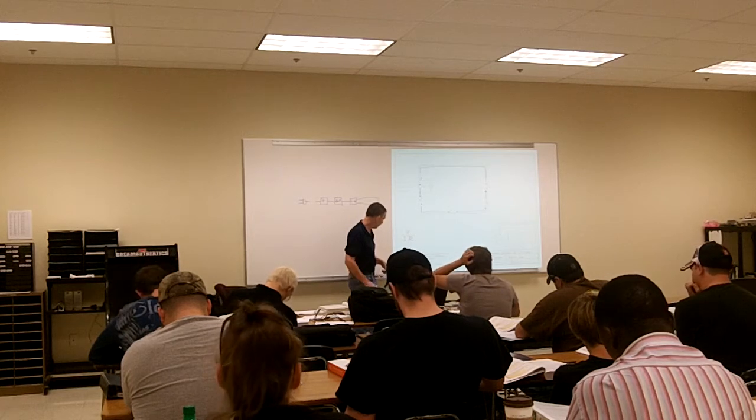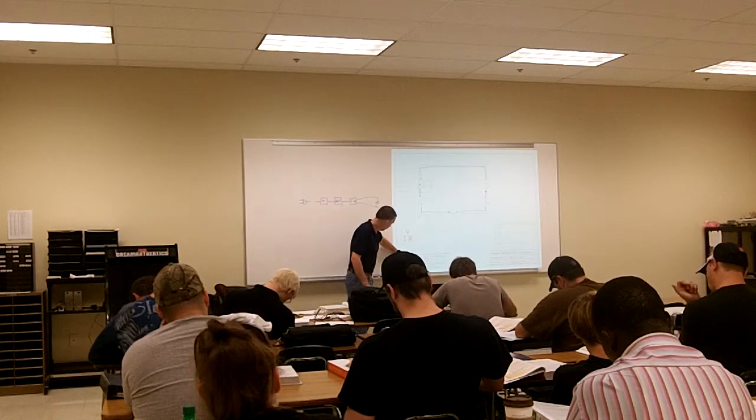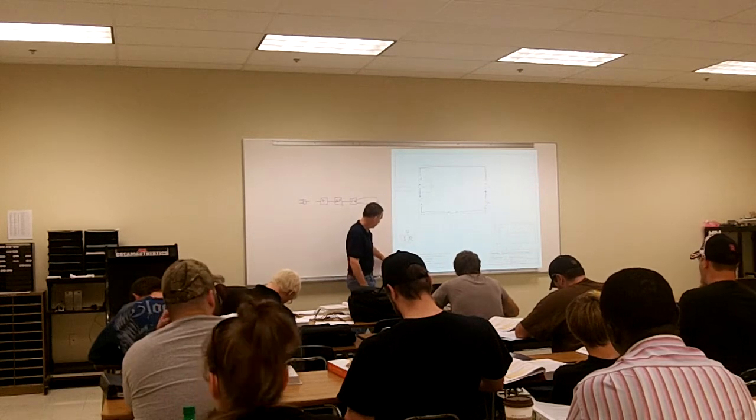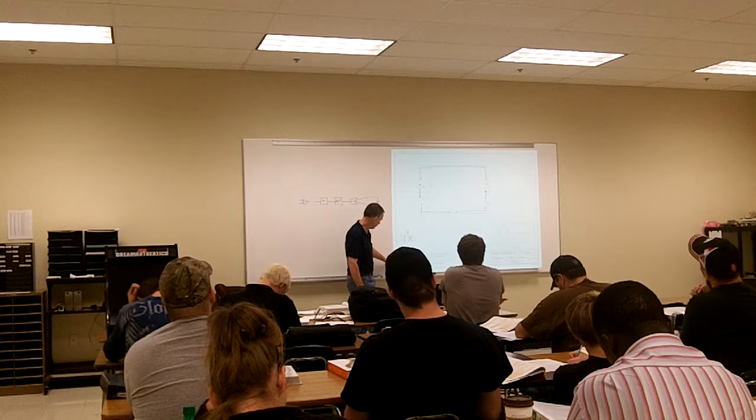Note number 4 says all resistors are plus or minus 5% tolerance. That's a typical note that you'll see on any schematic. Instead of them writing down the tolerance on all the resistors, they'll tell you what it is down in the notes.